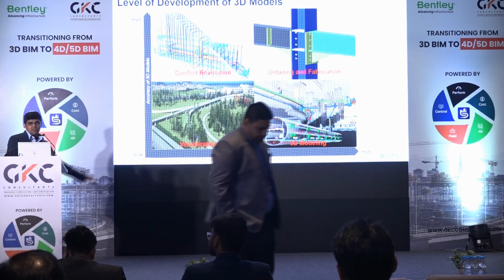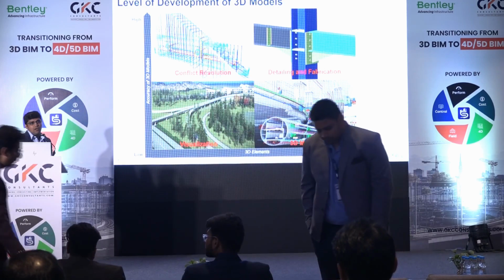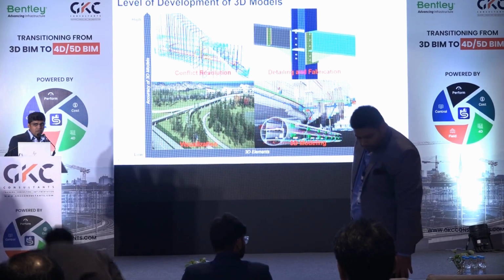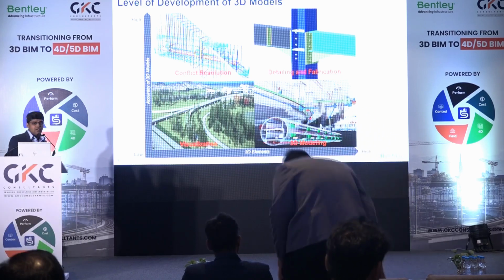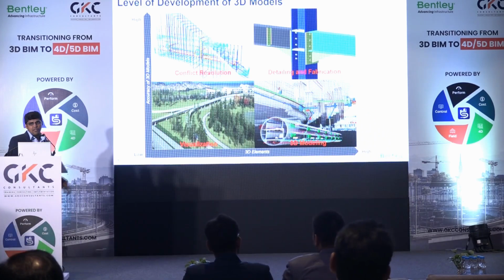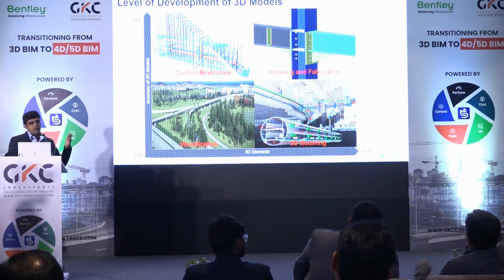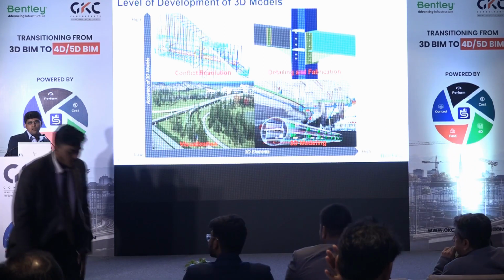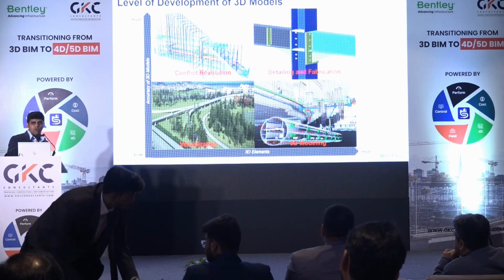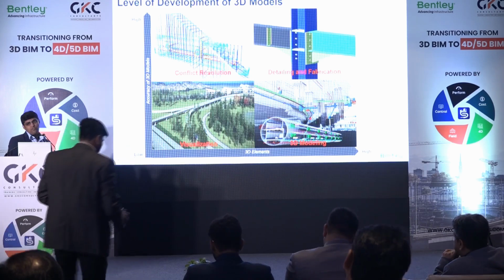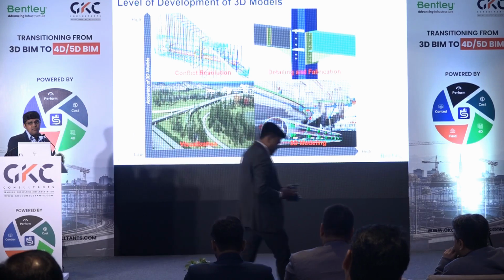What people do is consider this a 2D problem, take out their drawings, and for tunneling they do a 2D analysis. For the existing buildings, how much blast loading or excavation techniques would cause displacement or deflection in the existing structures, it doesn't care about that.